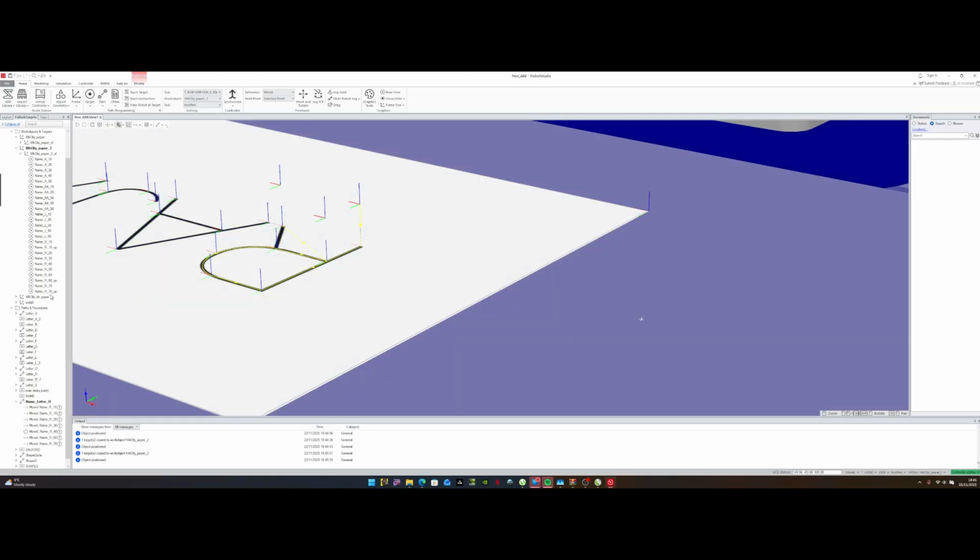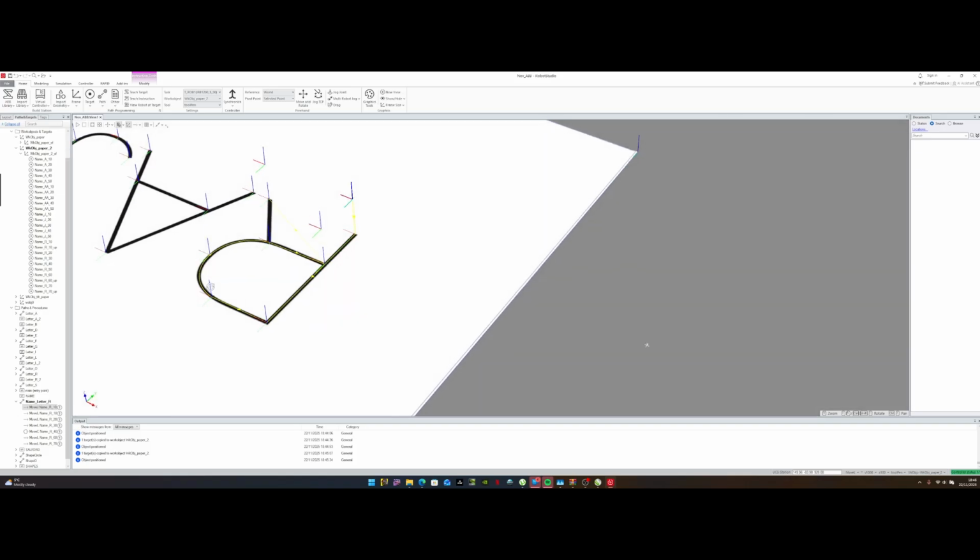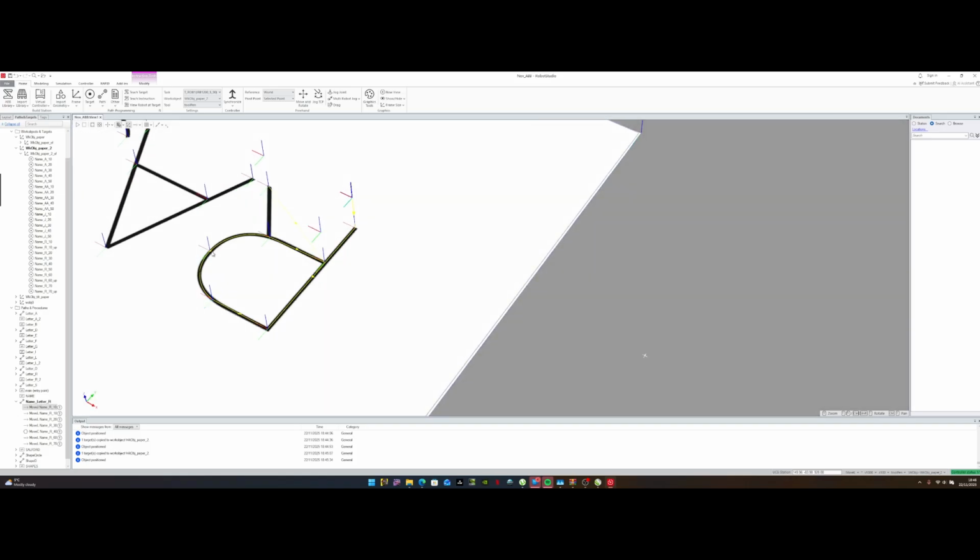Now let's continue. So again, robot jogs. If I go back to the path, robot jogs using move J to the first target. Okay. Then it goes using move L to R10, move L to R20, move L to R30, then move C through R40 to R60.